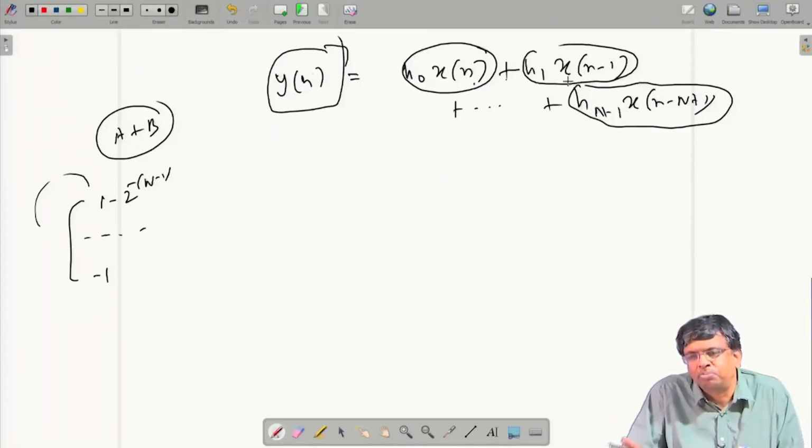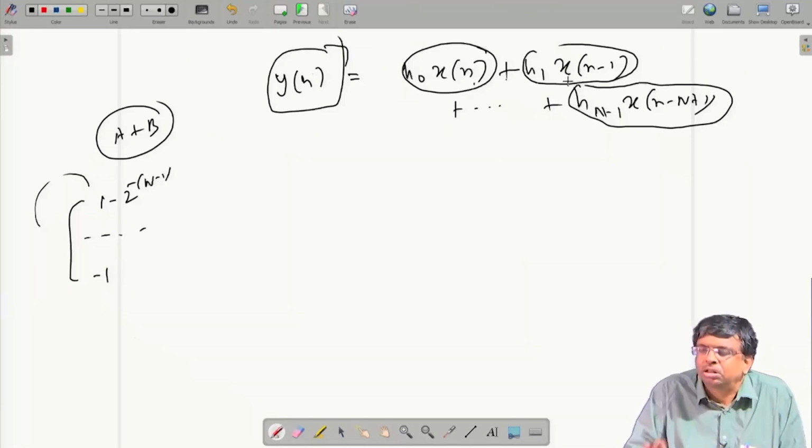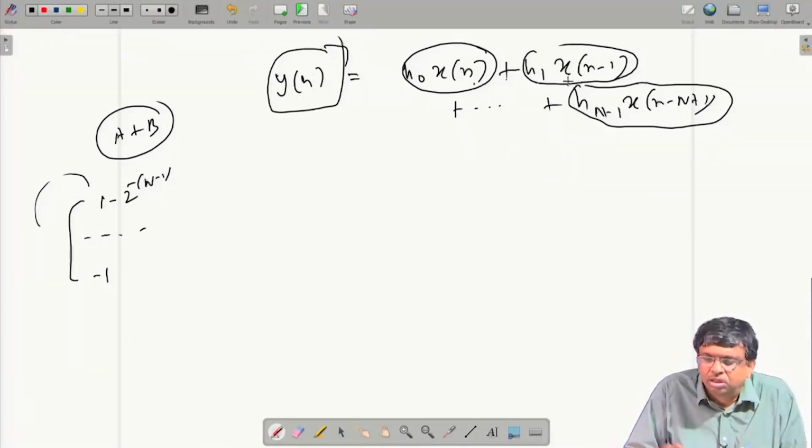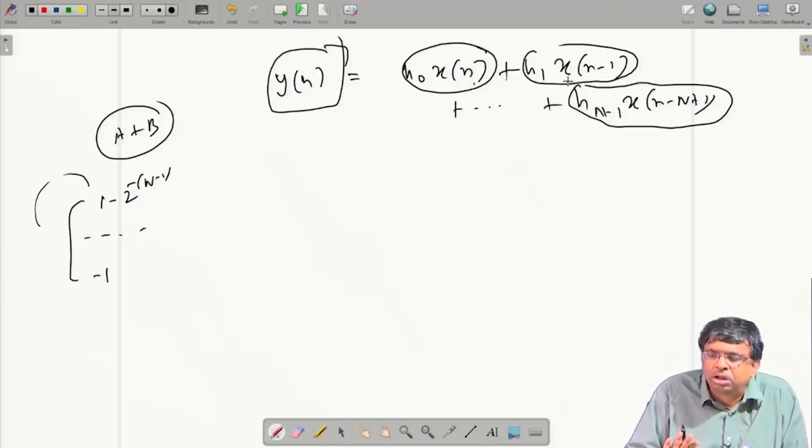Whatever result you are getting may appear to be wrong, but please move with that result. Carry on with the entire summation. Eventually, the result that we will get will be the correct y[n]. There is a theorem, it requires advanced mathematics, but that is the beauty of this two's complement number system. Whenever you are adding too many numbers, if the final number is guaranteed to lie between -1 and 1 minus 2 to the power minus (W-1), that is in the range of a W bit number, then even if there are intermediate overflows in some intermediate sums, you can just ignore them and carry on with your summation as it is. Do not have to worry, the final result will be correct.